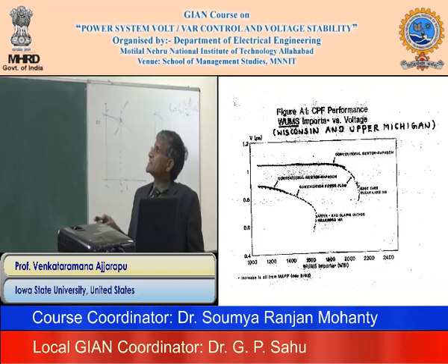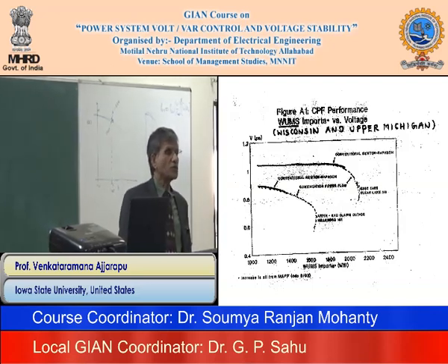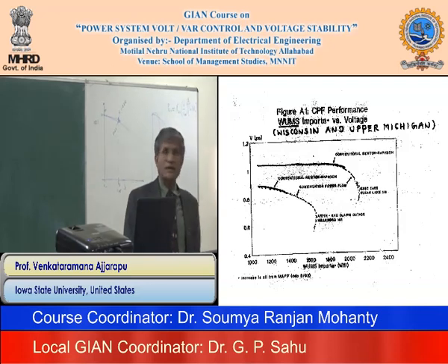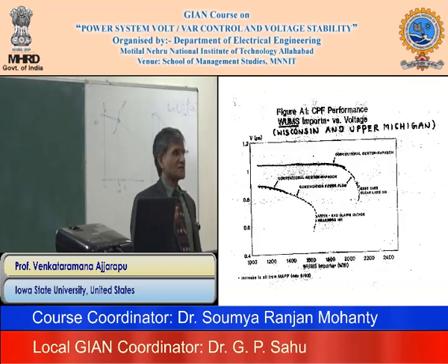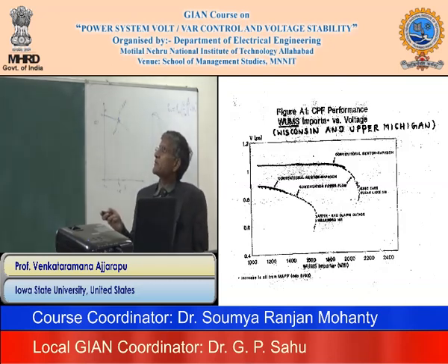But if you look at the contingency, it stopped here, so around 1300, but actually the maximum power is 1800, so about 500 megawatts difference. So that's a huge amount, because this is imports, remember? Imports and exports, that's business. So what we are saying is, if I use the conventional power flow, you said you cannot export more than 1300 megawatts. And we are saying that with correct one, you can export 1800.